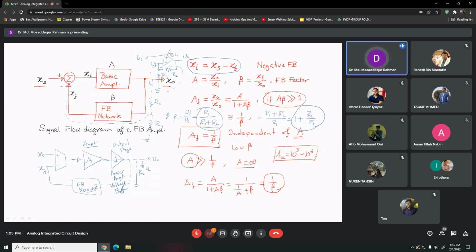In the case of op-amp, we have just 2 resistors here, R2 and R1. So we can also show it like this. We have R2 and R1, 2 resistors, and that just goes to this input side. So at the input side, this system here that takes the difference, usually we also call it difference amplifier.